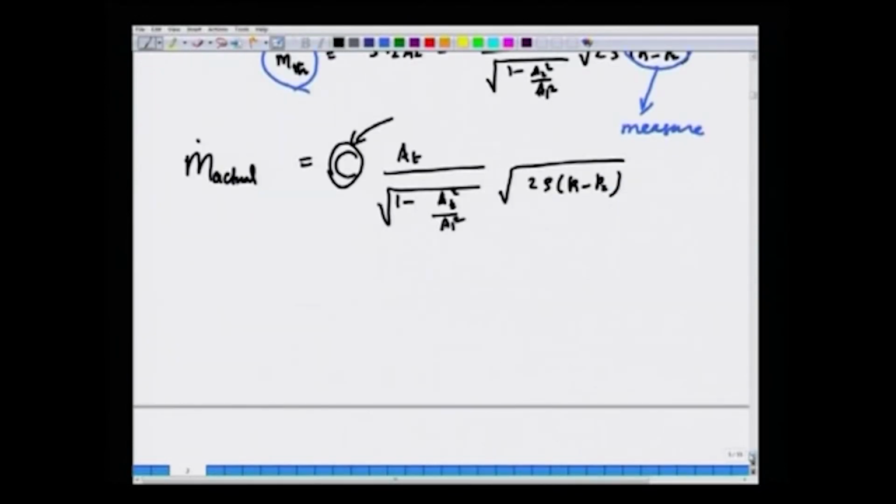We also mentioned that this is just a generic discussion, and in practice there are orifice meters and venturi meters which all fall into this restriction flow meter class of flow measuring devices. But one drawback of restriction flow meters is that you will be able to measure only the average velocity, the cross section average velocity over the entire cross section of the pipe. But suppose in some applications you need the local velocity at a given point in the cross section of the pipe, then what do we do? Okay, so this is where we left off in the last lecture.